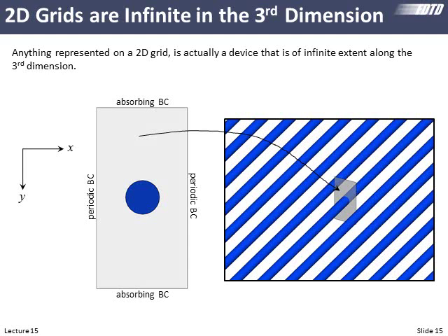So here's another picture. If first we're handed our 2-dimensional grid and we see a little circle here, very often in the literature they'll call that a cylinder. Well, why on earth is that a cylinder if we just have a 2-dimensional simulation? Remember that 3rd dimension, in and out of the screen here, really is infinitely extruded. So this kind of array is really what we would be modeling with this little unit cell in memory, a periodic array of cylinders. That 3rd dimension is infinitely extruded.